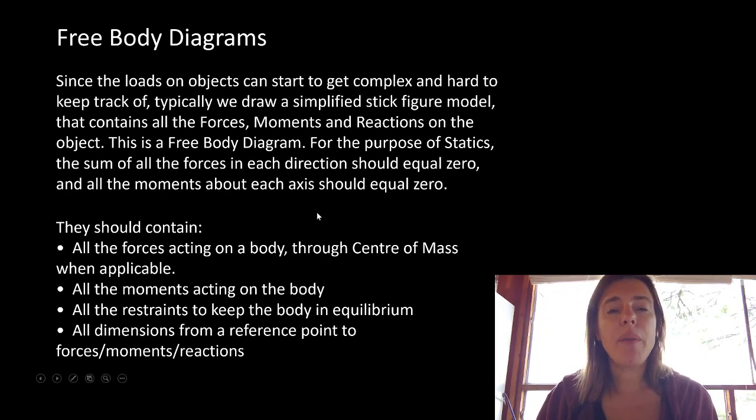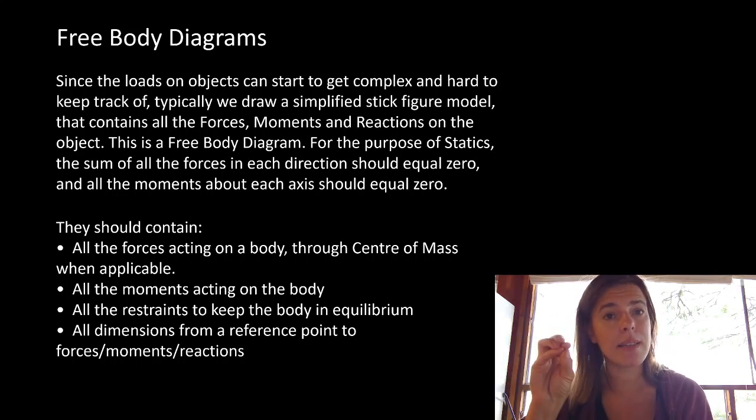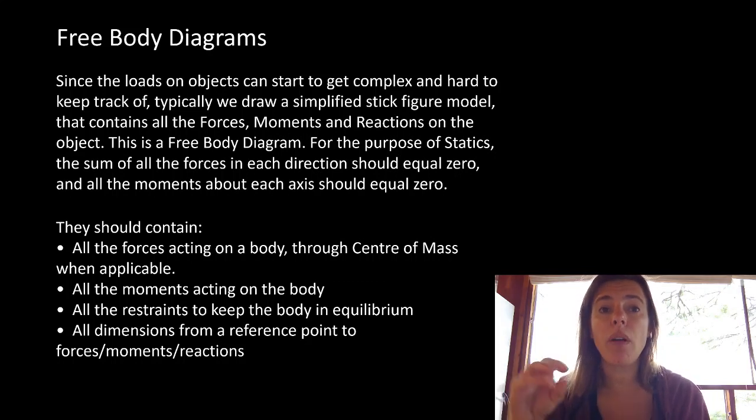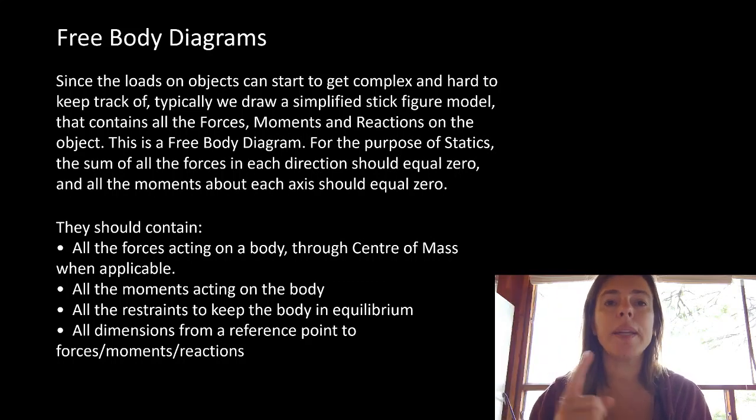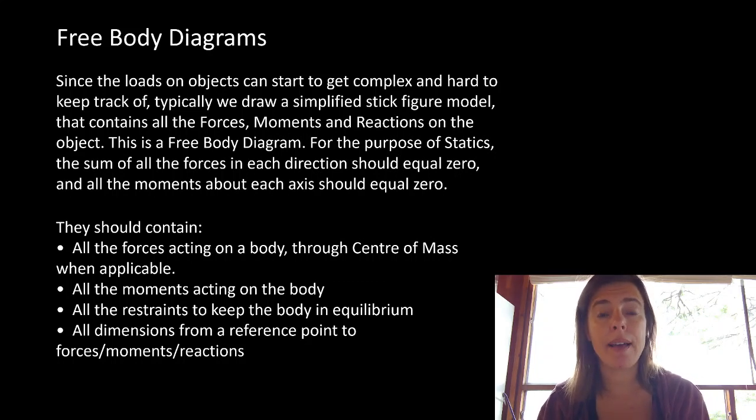Free body diagrams. Free body diagrams are a really handy tool to take a complex system and distill it down to a very simplistic drawing to make sure we understand what all the loads are on it and how we're resisting these loads. Even still, sometimes senior engineers can't solve a problem. They take a second to draw the free body diagram, and it kind of crystallizes the idea: oh, I need a reaction here, so I need to put something there that can resist the load there. And so we do that often by drawing a simple stick figure and representing all the forces and moments as vectors.